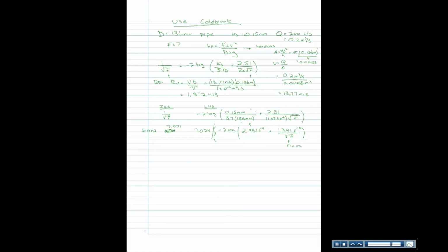They're not exactly equal. If they were equal, then that would tell us that we had the correct value for f. So we're not there yet. Let's just say, by the way, the range of possible values for f is 0.008 all the way to 0.038. Those are sort of the likely ranges of f that we're going to see. So knowing that range gives you an idea of where to start. I just sort of picked the middle value here.